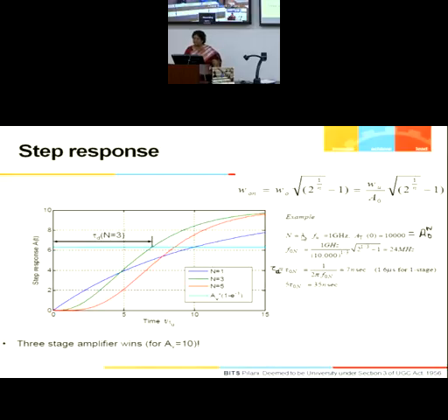So if I substitute everything in this expression, we get omega naught n. I am getting f naught n because you would be then dividing by 2 pi. Okay. This comes out to be 24 megahertz. For 24 megahertz the corresponding tau comes out to be 7 nanoseconds.